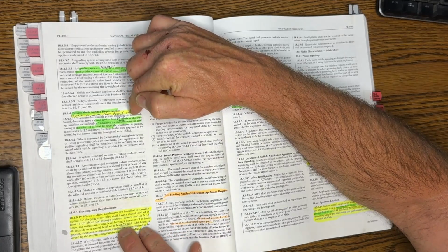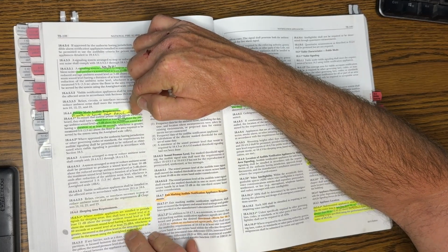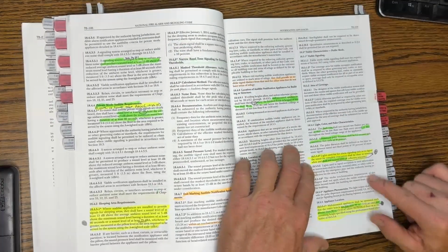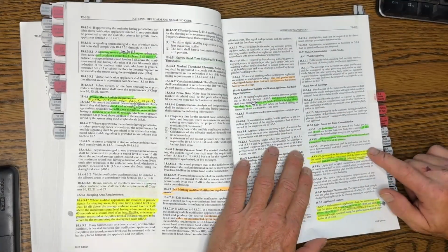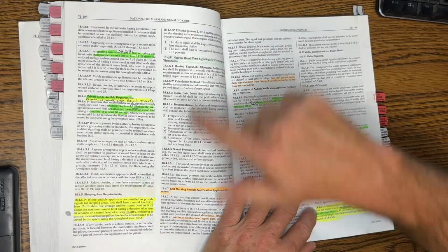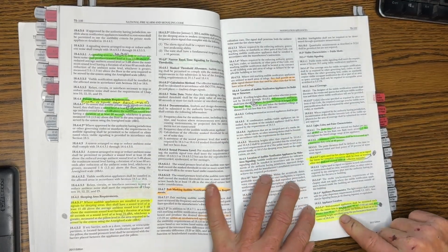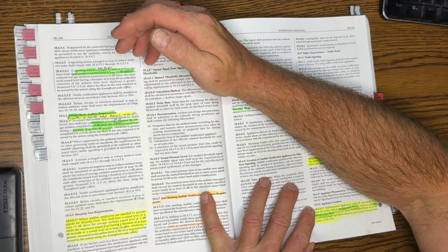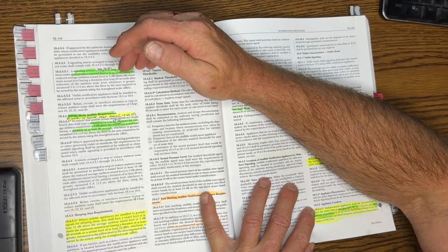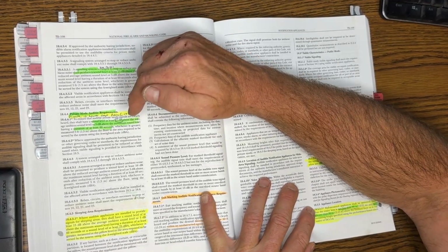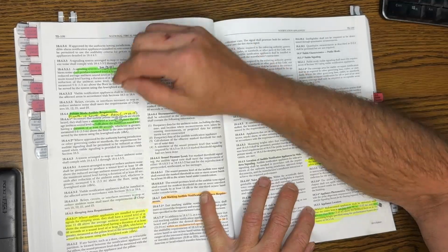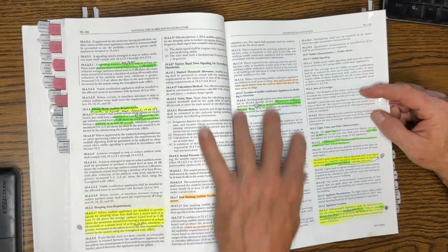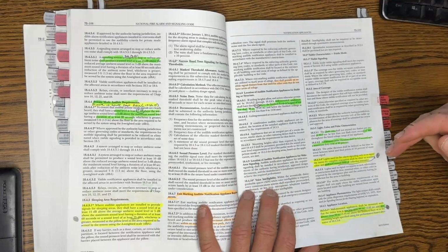Let's see. 10 versus 5. There's 75 dBA. Okay, sleeping area requirements is 75 dBA. Look there. 100 candela. Look here. So there's a few references all on the same page. But I don't have it marked, but just keep in mind the maximum sound level for a fire alarm system notification appliance is 110 decibels, but it's not highlighted. Just keep that in mind. It does come up in other places occasionally, and it might come up in this test. It's a frequently asked question.